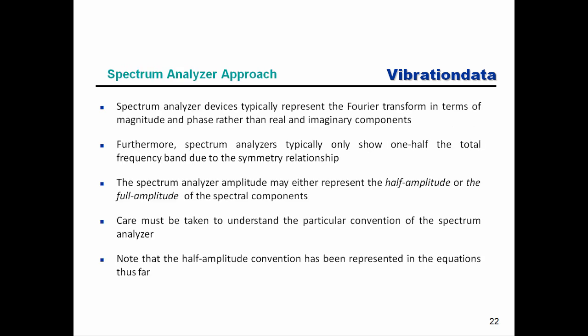Okay. So let's talk about spectrum analyzers. The spectrum analyzers we use for engineering purposes, and wouldn't it be nice if mathematicians could get their hands on spectrum analyzers and develop some empathy for us as engineers? But anyways, typically our spectrum analyzers are going to represent the Fourier transforms in terms of magnitude and phase rather than real and imaginary.